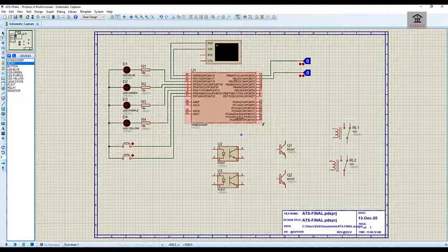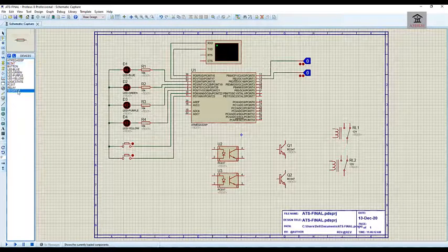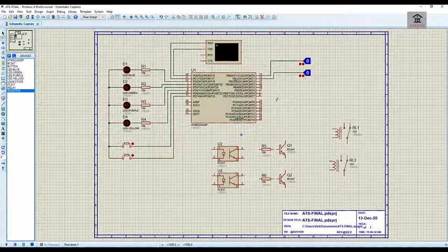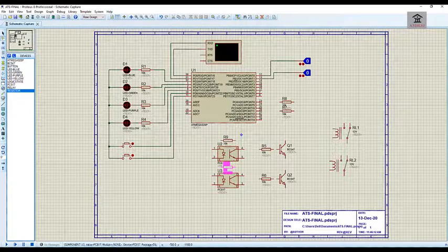And then I now need to put resistors on some inputs. So I'll come here and then select the resistor I had previously used, and then I'll put one on the base of this transistor, put another on the base of this transistor, and then I'll be putting one on the point where I'll be connecting my relay from, and then I'll put another one for the second relay. I'll be needing some resistors for the opto isolator as well. So I'll put this one here like this, and then I'll put this one here as well like that.